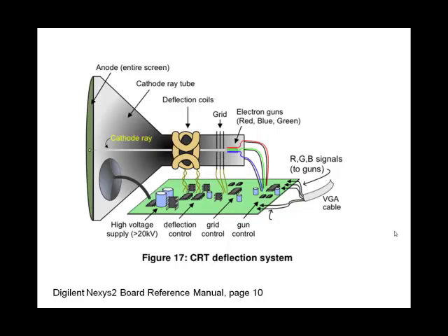You're going to create a controller for a cathode ray tube, or a CRT. Even though we don't use CRTs anymore, the timing and control signals of the VGA cables use the same protocol for a CRT as they do for the LCD, for backward compatibility. It's helpful to understand how a CRT works in order for you to understand the timing signals and the video signals you need to create.